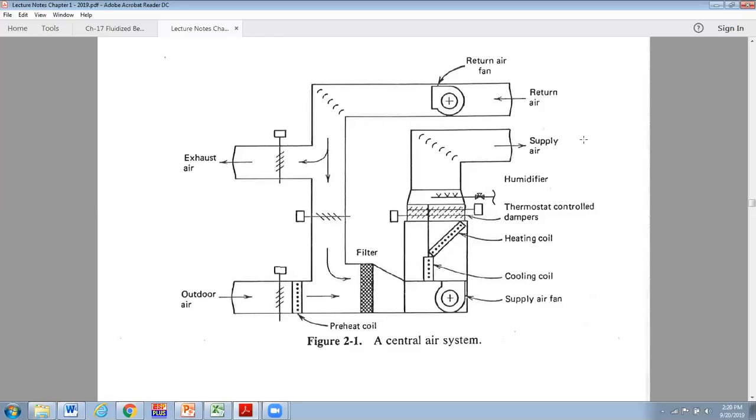This is if we energize both the heating and cooling coils at the same time and they mix air, that is a form of reheat, which would be fairly expensive in terms of operating cost. Tennessee Tech has some systems like this, and sometimes in the summer, you just don't run the heating, don't allow the hot water to go to the heating coil. Go ahead and run the chill water, and if there's any mixing here, this would just be return air that's mixed with ventilation air, and you could temper this a little bit.